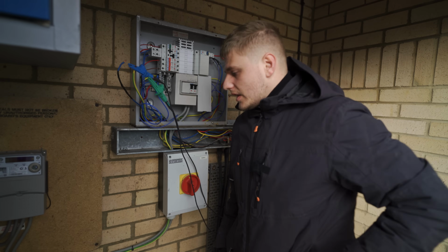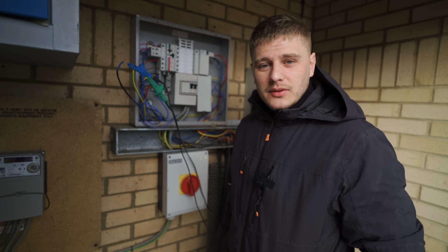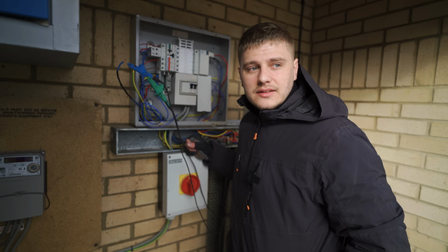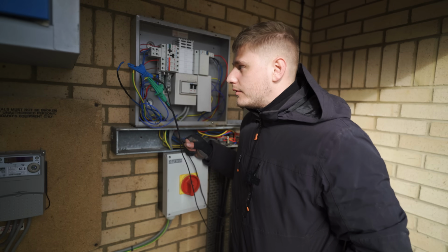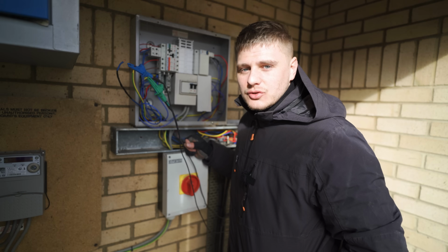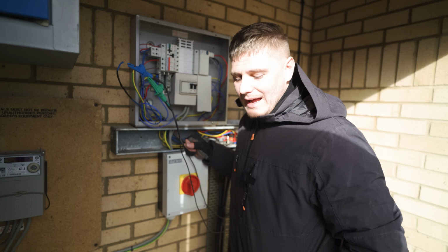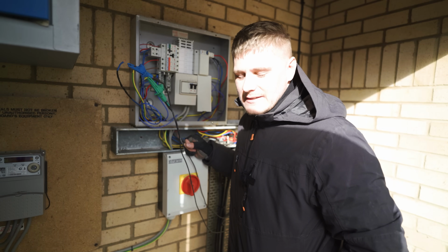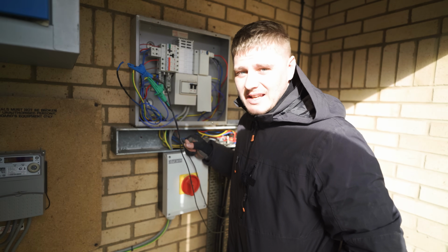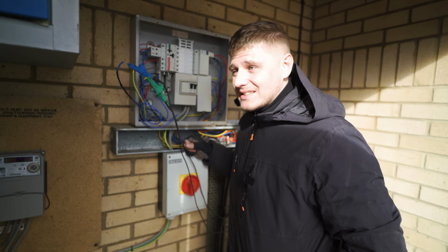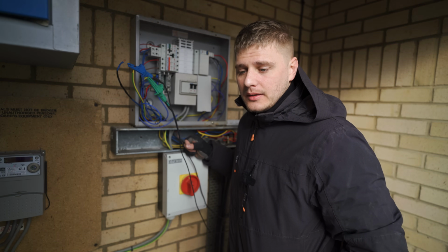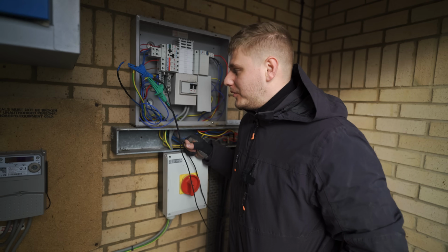Now you've got connected loads in all the lampposts, so that's going to be the majority of those issues. And then obviously if you had a live earth or a neutral earth issue, that's going to add parallel paths to that dead short as well. So what I've got to do now is go round and, hopefully, remove all the low level fuses, which will isolate the loads. Give it another test, and if there's still shorts there, then I'll actually have to unwire it all and start breaking it down. But that's part of the fun with this sort of fault finding.